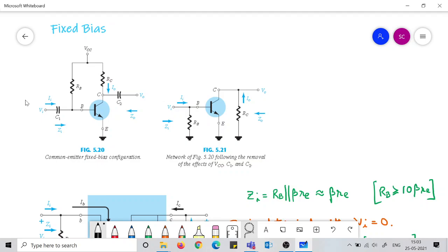Then all the DC sources were made to 0, and in the circuits that we deal with, we normally don't have current sources, we have voltage sources. So a voltage source becoming 0 means it is grounded, and the resistances which were connected to the source previously are now connected to ground, and in that manner the entire network changes and we arrive at the AC equivalent circuit.